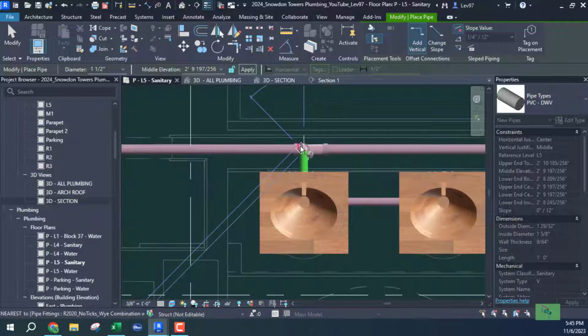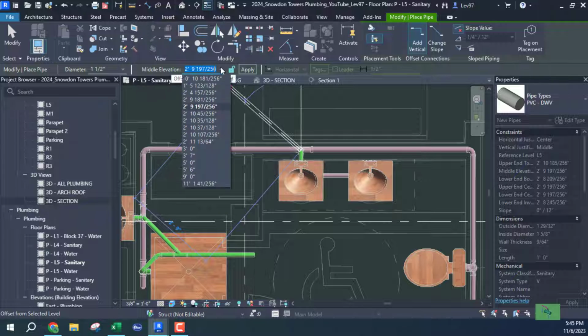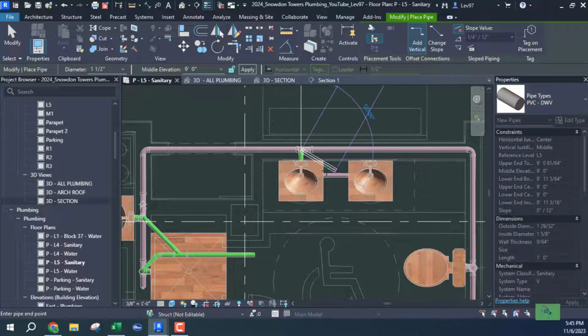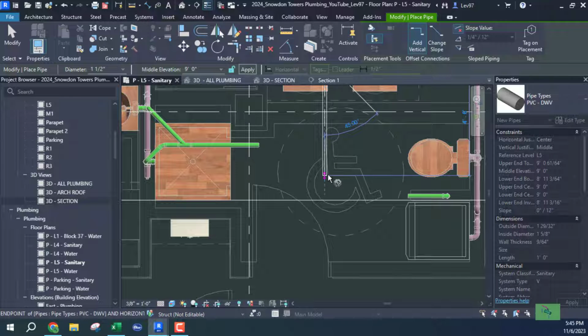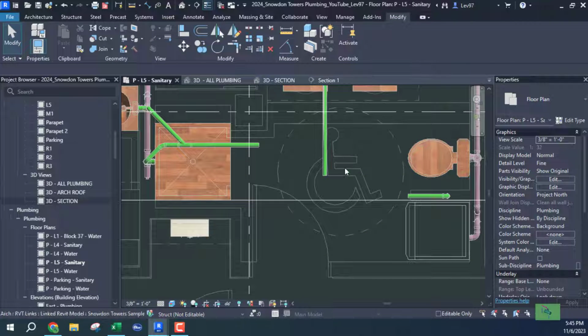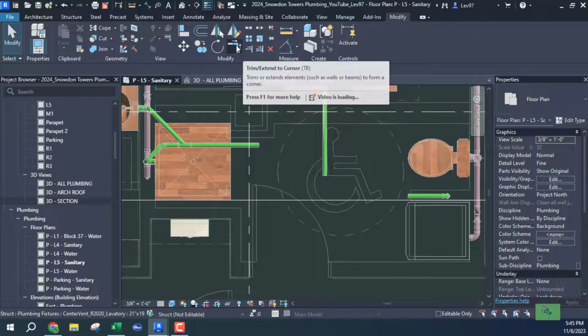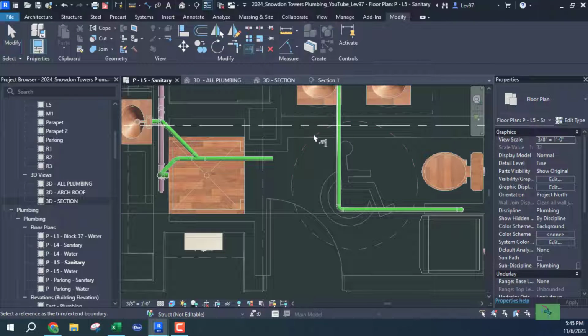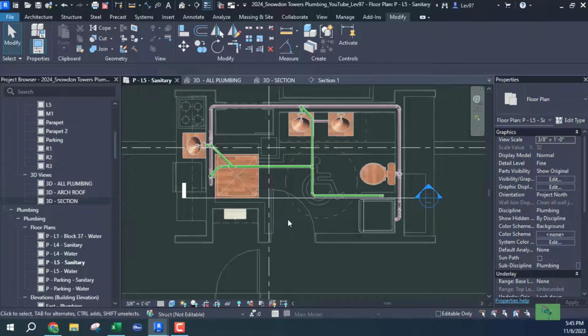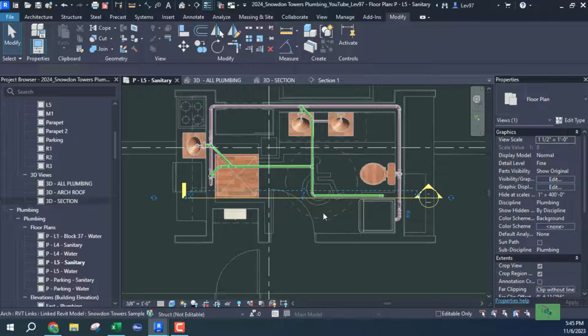And now I'm going to come up at 9 feet, right? I'm going to get in the ceiling at 9 feet and come out at 45, which makes that 135, and come down, okay? And I think this is a better layout, okay? So we can connect here and connect here. So I'll fill it and extend. Let's fill it. Okay, and let's extend this pipe, that pipe.